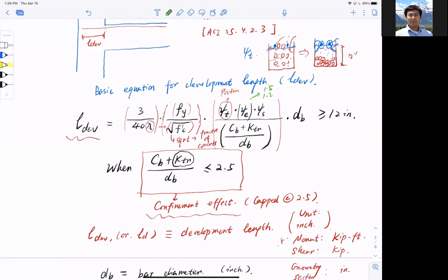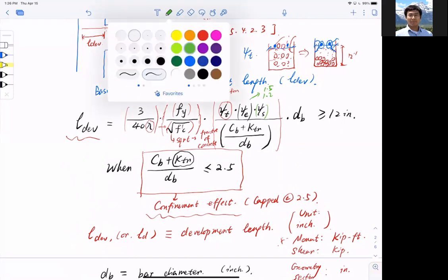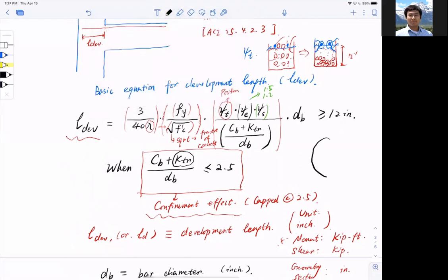And last but not least, psi S, which is a bar diameter property. Why is that? If I have a bar, and this is a zoomed-in portion, I have ribs. Although the ribs were built in such a way that they are proportional to the diameter of the bars, the larger the bar, the more non-uniform the stress distribution across it.